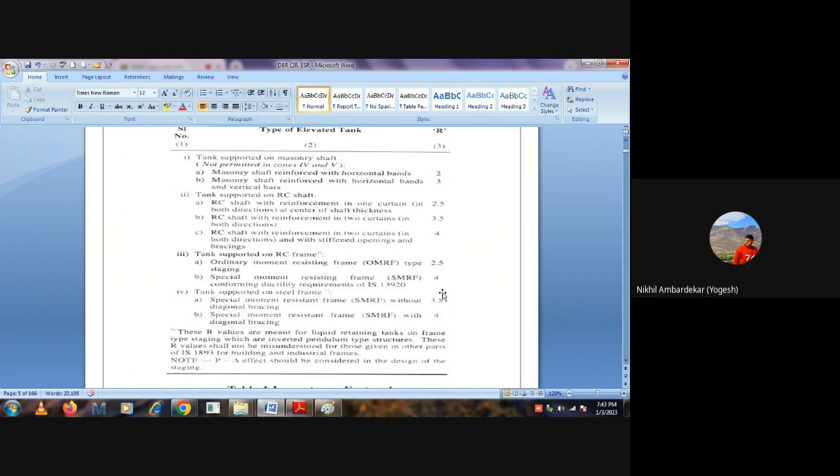So what are the ductile requirements? Based on IS 13920, it is part of the detailing. When we start creating structural drawings, we have to follow that ductility requirement. So for earthquake, I will ask you one question: which is the better detailing practice, rigid or ductile? Ductile, sir.